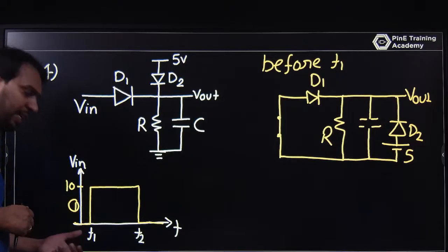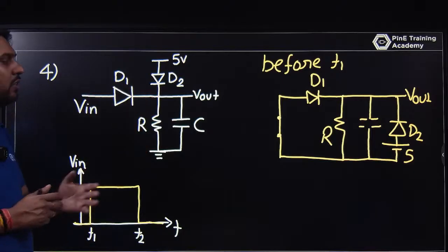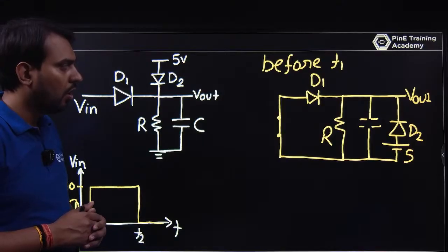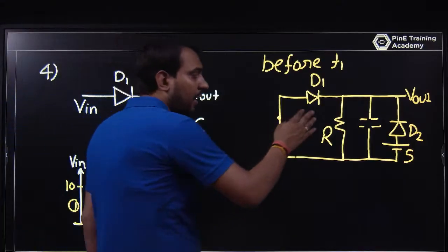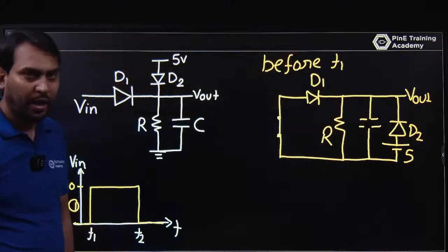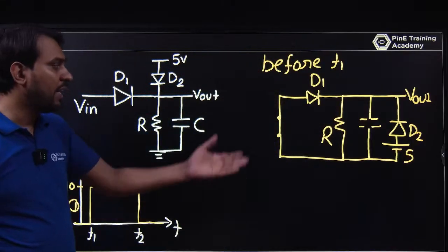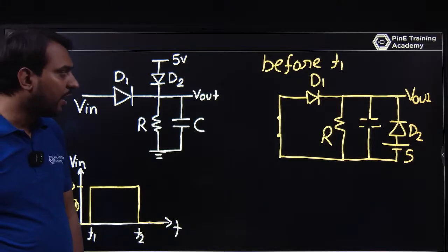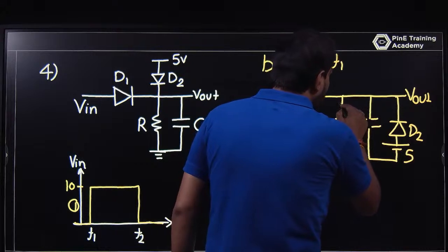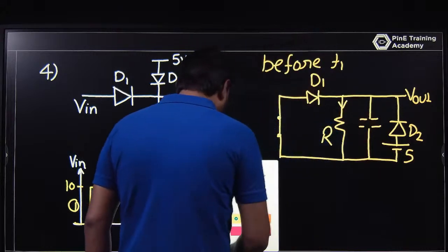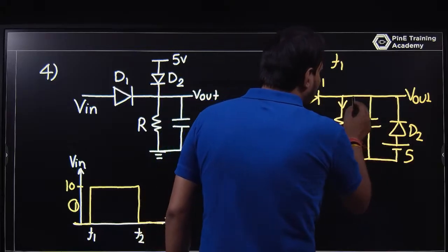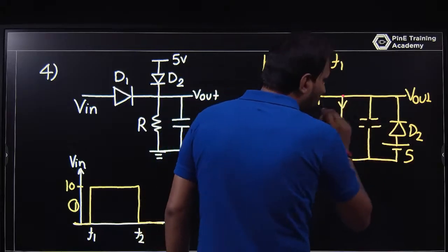So in a DC state the capacitor acts like an open circuit, so I make that capacitor act like an open circuit. What is happening? The capacitor will take any voltage across it because it will be open, and that will be limited by the resistor or that circuit. So I am thinking, if there is any current, there is no current here because there is no external supply.